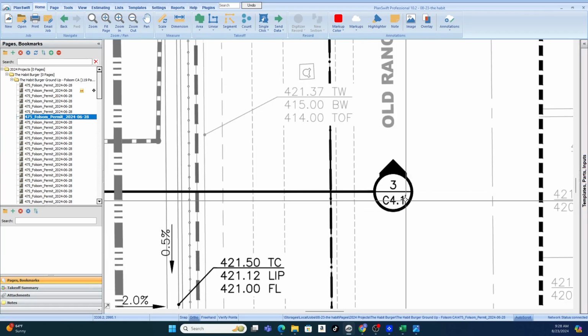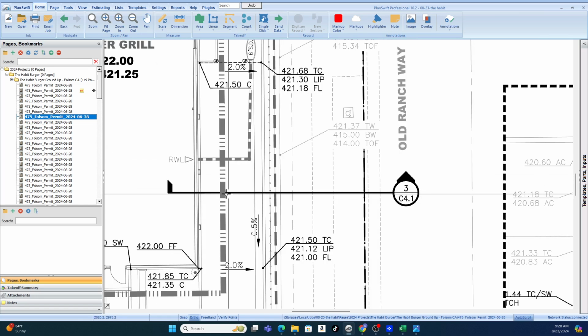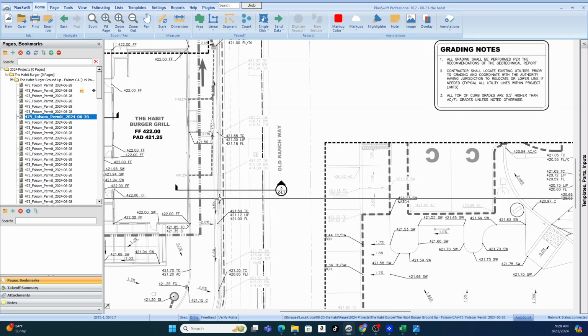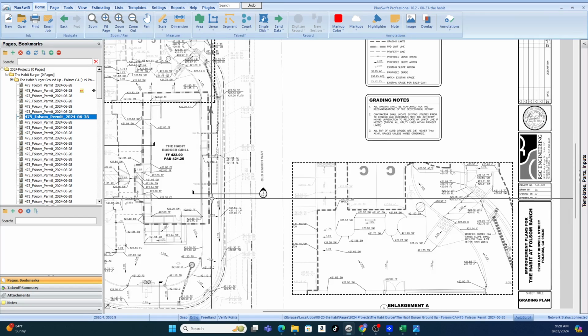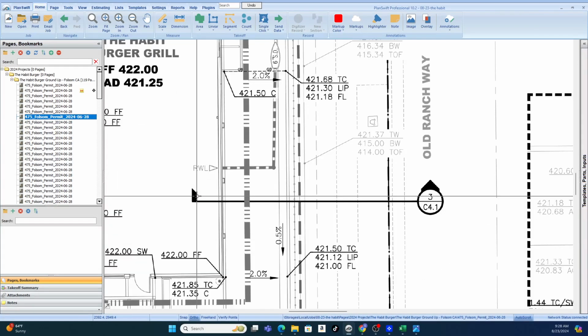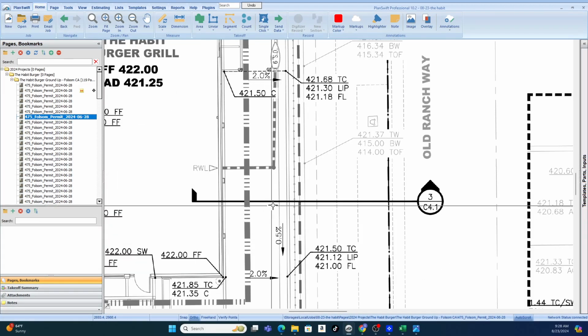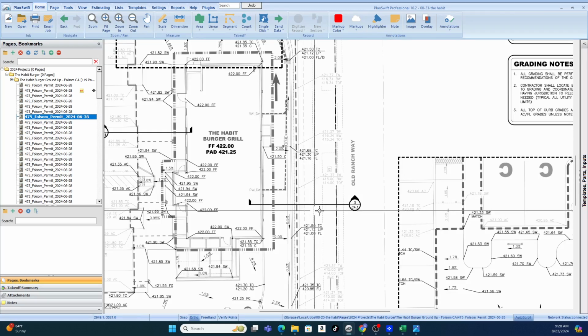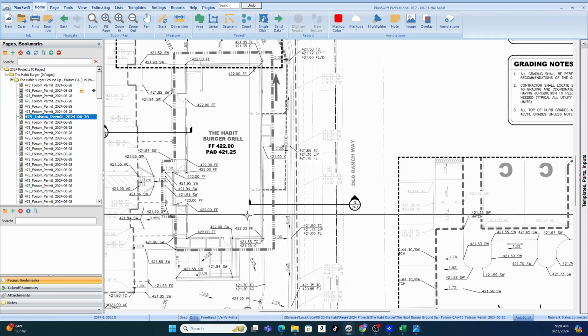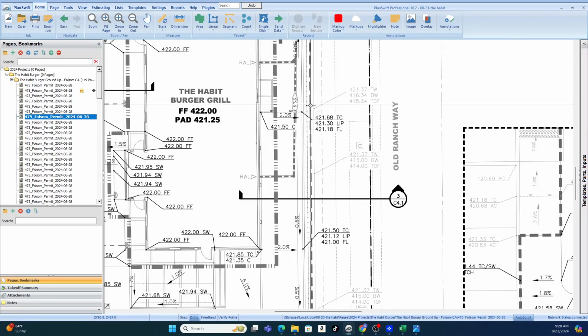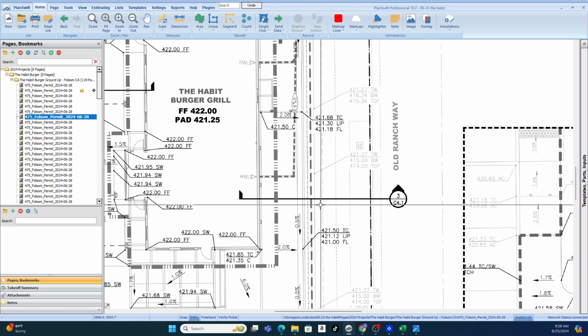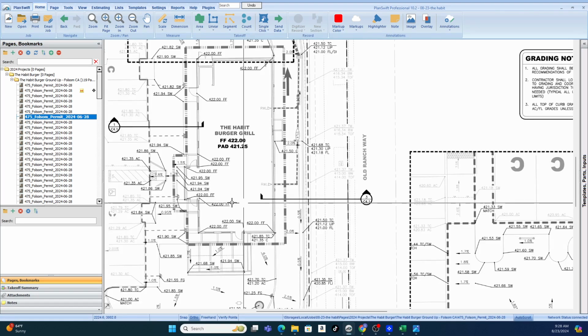Section view markers: the circle, the hat, the leg, the foot. You'll see this in the civil set and the architectural set. It really doesn't make a difference because it's one of the views. It's a view that the architect wants to give you a fuller understanding of what you're looking at. And the understanding is whatever the leg is going through. So the leg is going through our foundation footing.